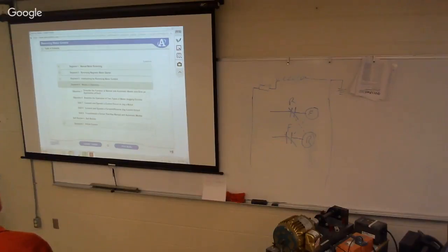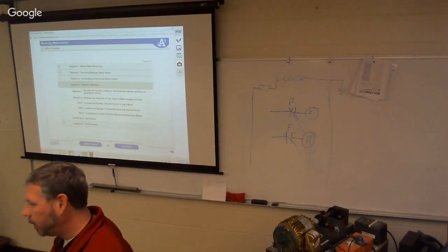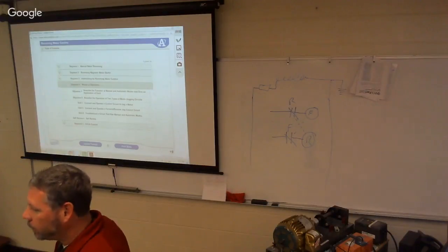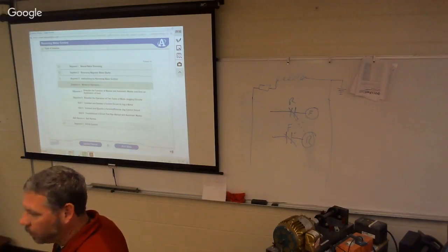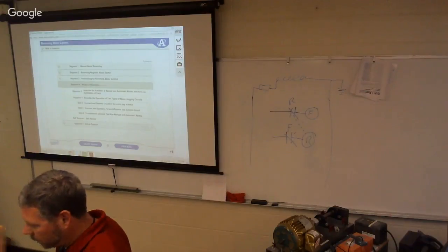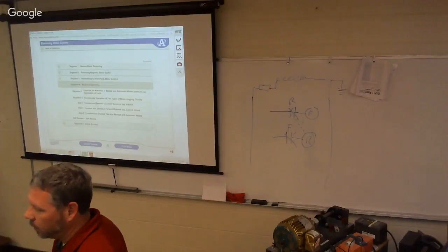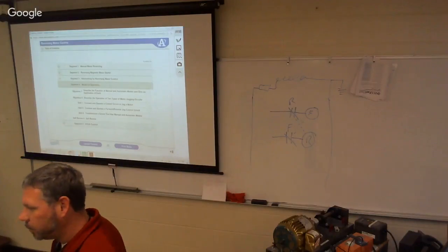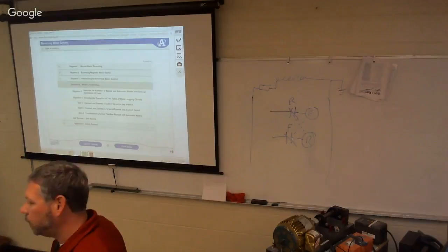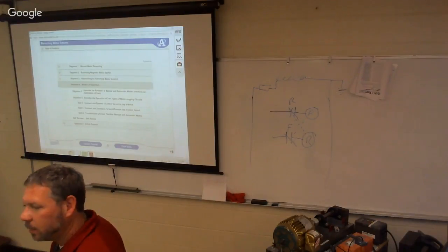And then I'm going to begin testing you out on the start-stop. We'll set up a little camera. I'll bring my laptop in there. One at a time. This will take several class sessions. Those of you that are comfortable with doing it, I'm going to film you. You're going to put on your arc flash when it's hot. You're going to wire it all up, start-stop. You're going to draw it out, wire it up, show the camera, and then I'll put in 2 faults. You'll troubleshoot them in front of the camera.